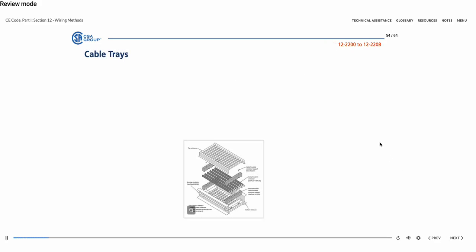Cable trays offer an economical and sturdy support structure for service, feeder, and branch circuit cables, mostly used in industrial, commercial, and institutional construction. The code does not give specific support requirements for cable trays. Instead, it requires that cable trays be marked with the applicable load and span ratings, as determined by testing to the Part 2 standard.